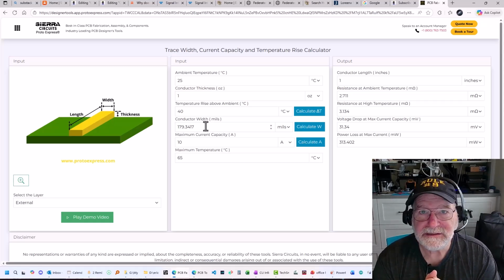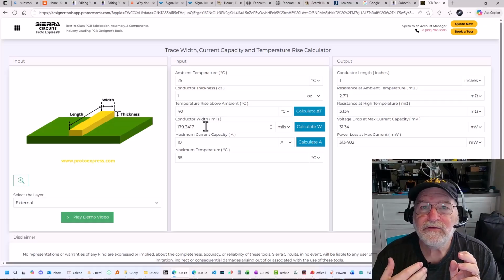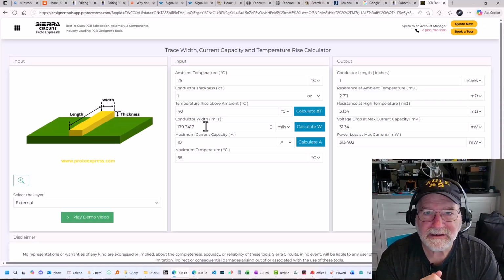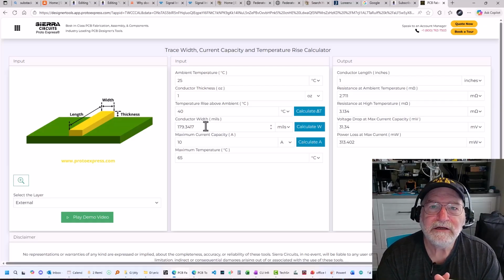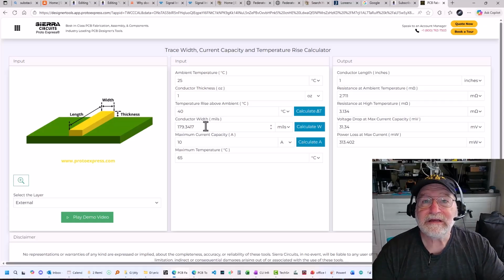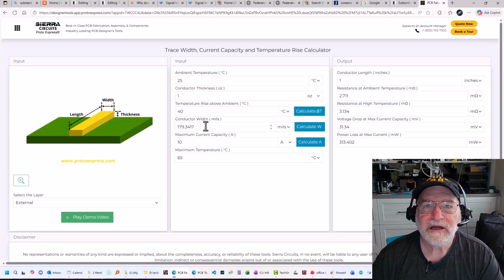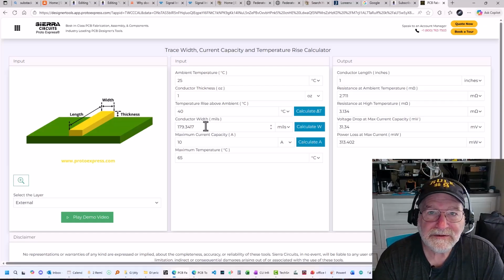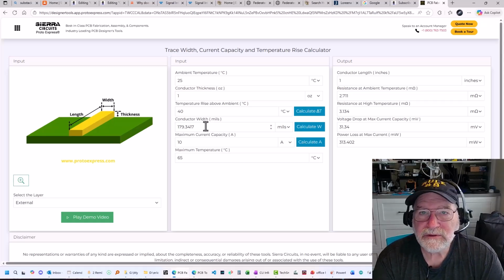And I always recommend, if you're doing 3 amps, which is a lot of microcontroller based IoT kind of designs, a maximum of 3 amps at any time, even a 20 mil wide line is all it takes to distribute 3 amps of current. And at any point, if you're concerned about this, you want to convince yourself that's the case, you want to use a simple little test board that allows you to send a few amps of current through a test line and measure what the temperature rise is.